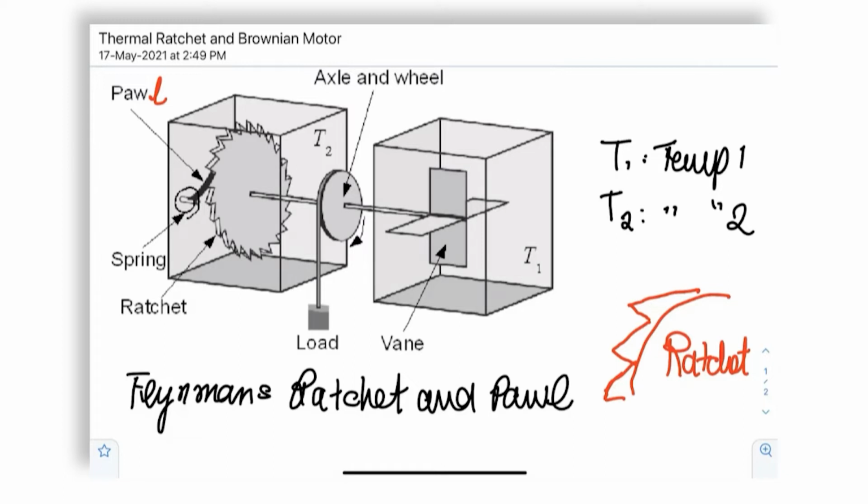The job of the pawl is exactly that, but not in the other direction. That is to say, you can turn it in this way, but in the opposing direction, there's an enormous penalty due to the presence of this latch or pawl, which itself is spring loaded. So you can keep turning it ahead, but you can't turn it backwards. Got it? Okay, one directional movement.